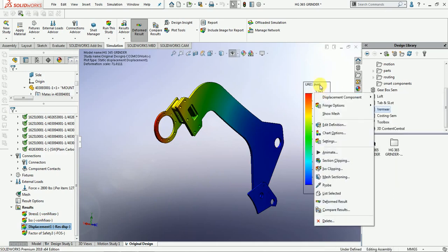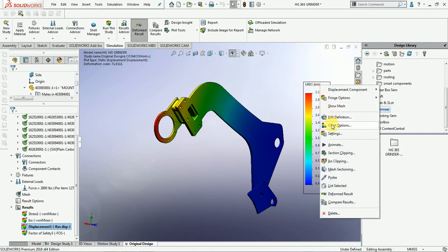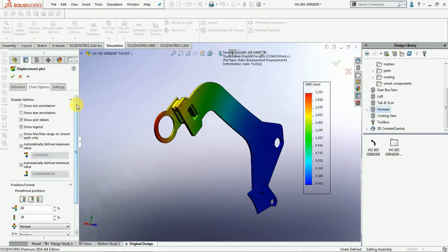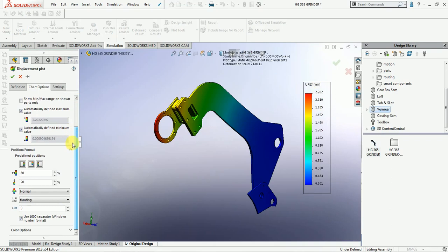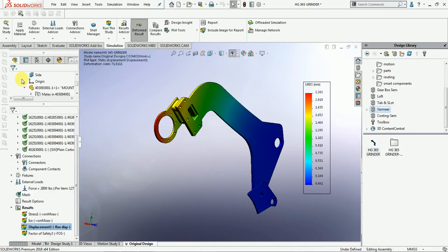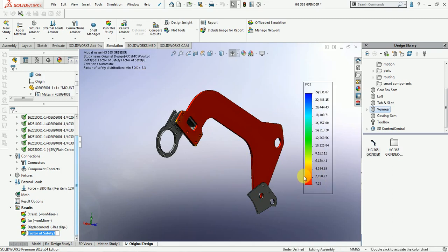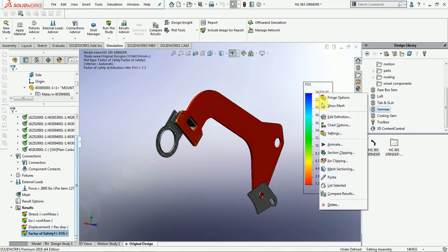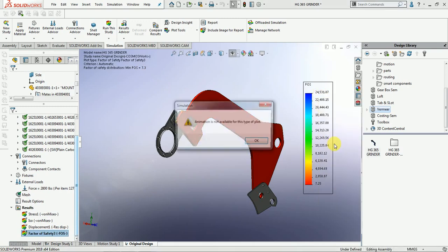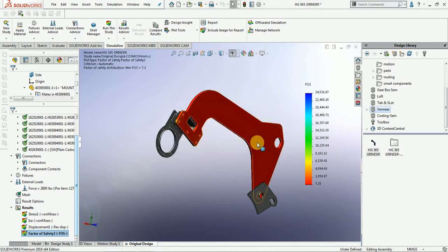My deflection is 2.202 mm, and the results match approximately 95% of the real-time results. For factor of safety, fabricators usually keep 2.5 times the real-time material. Here my calculated FOS is 7.3 times. So if I need to reduce the thickness of the sheet metal, I can work on the models with dependency on the chart on the right-hand side.